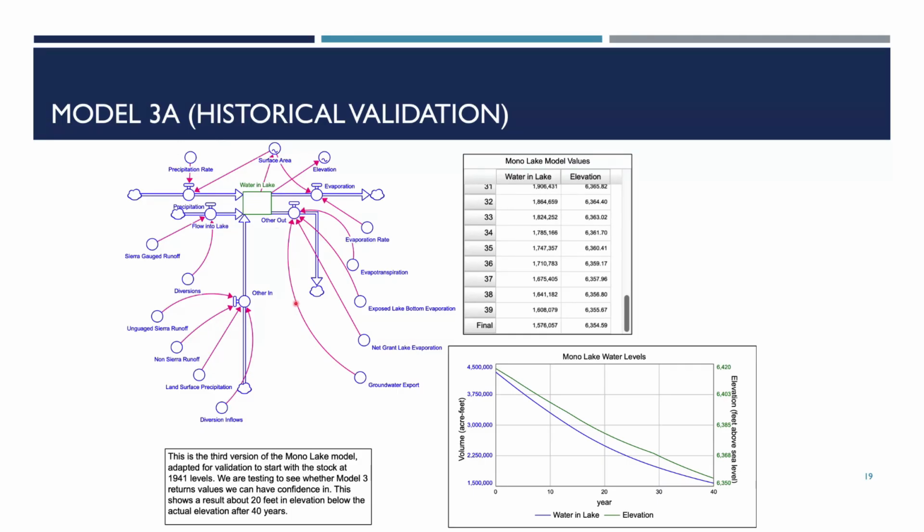And as it turns out, the fixed value is the evaporation rate of fresh water. So saline water evaporates more slowly than fresh water, and we're not accounting for that. So we're not only using a too aggressive evaporation rate to start with, but as the lake level drops, that evaporation would continue to decline, and we're not getting the feedback of that over time.